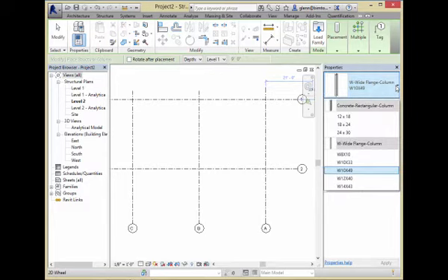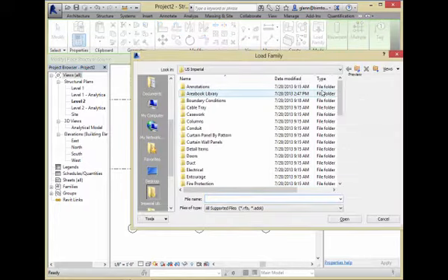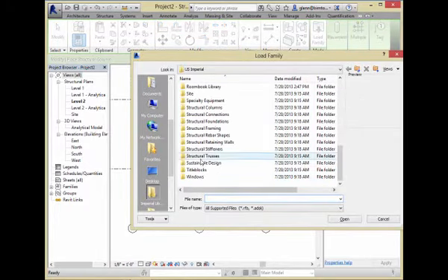And they have a couple of standard shapes in there right now. There's a concrete column and a wide flange column in there. If you don't want these shapes, we can load in some more. We'll show you how to load in some more wood or concrete columns or wide flange columns. These are some standard profiles that are available. If you need to load anything, we can load them in from the library. They live in the Structural Columns section.